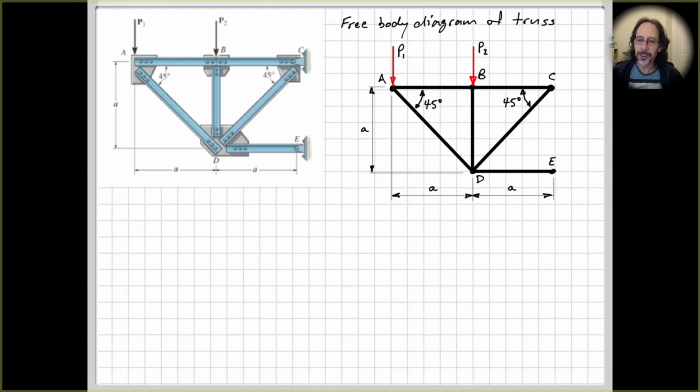Okay, so we'll start with something that we know. We'll treat the entire truss as a rigid body, put in our values. So our rigid body, free body diagram over here. Now we need to just put in the reactions that are generated by the supports. Down the bottom here, this is a pin connection, but I'm pretty sure I only put a horizontal force here. Right, yes I do. So let me go back and explain why.